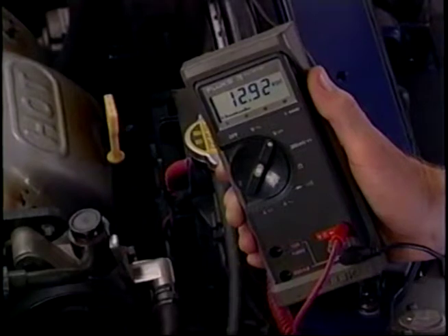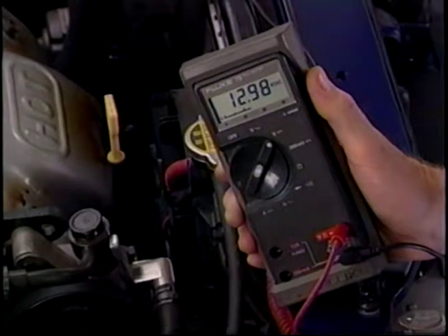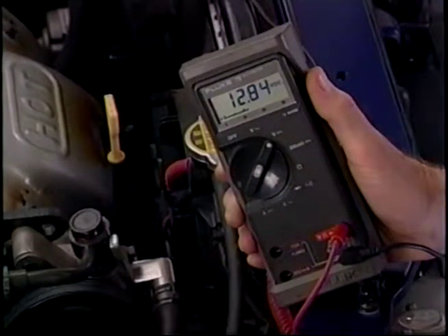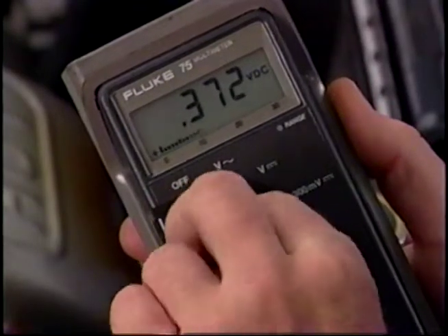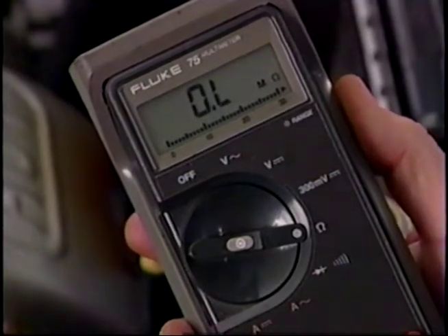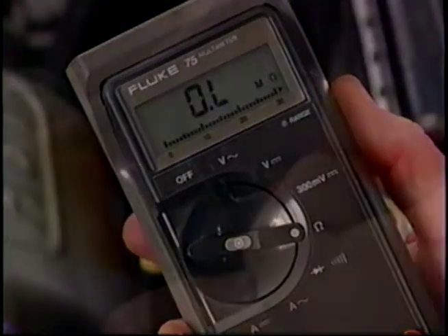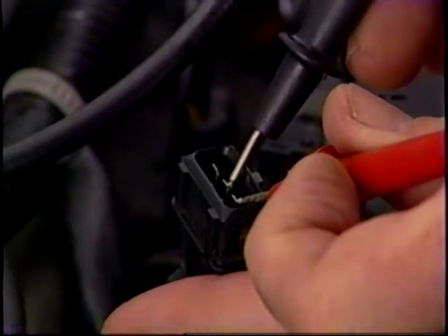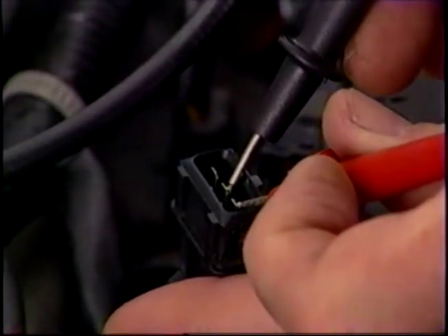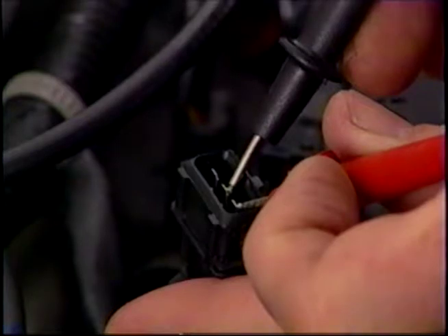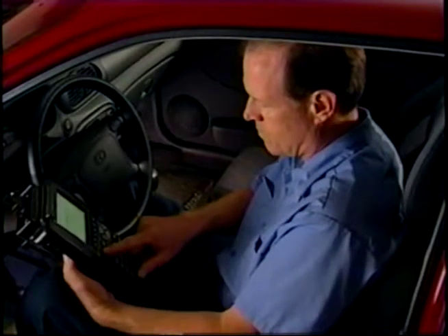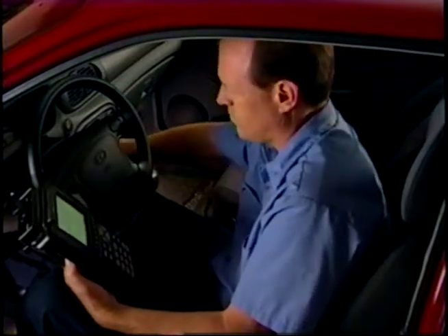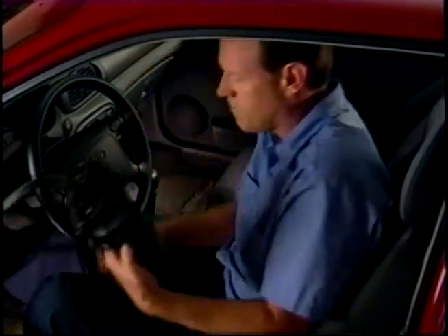In most cases with DTCs, you will have to use a digital multimeter to check the reference voltage to the sensors and the return voltage to the PCM. The ohmmeter function can be used to test the resistance and continuity of the sensor. Voltage drop tests should be done across connectors and components to check for excessive resistance that could alter sensor input or actuator output signals. Once you have verified that your repair is complete, make sure that you connect a scan tool and clear any codes that may have been generated during your repair.